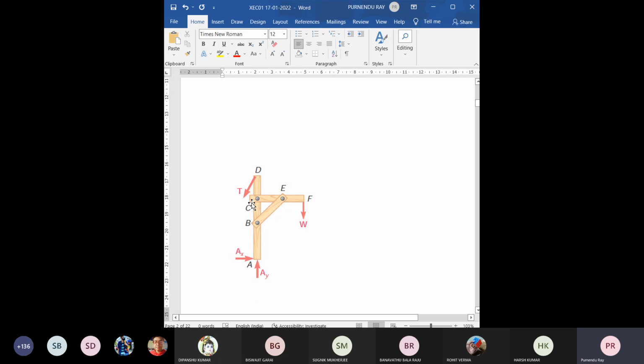From this diagram, this is not a concurrent force system as usual. It has got 3 unknowns, and for a non-concurrent coplanar force system, you can develop 3 equations of equilibrium, 2 force equilibrium equations and 1 moment equilibrium equation. So solve it. So T, RAX and RAY, or in some books you will find the notation RAH and RAV representing reaction at A horizontal component and reaction at A vertical component. So whether it is RAX, RAY or RAH, RAV, doesn't matter. You should understand whatever notation you have used, follow it accordingly, and nothing to get confused.